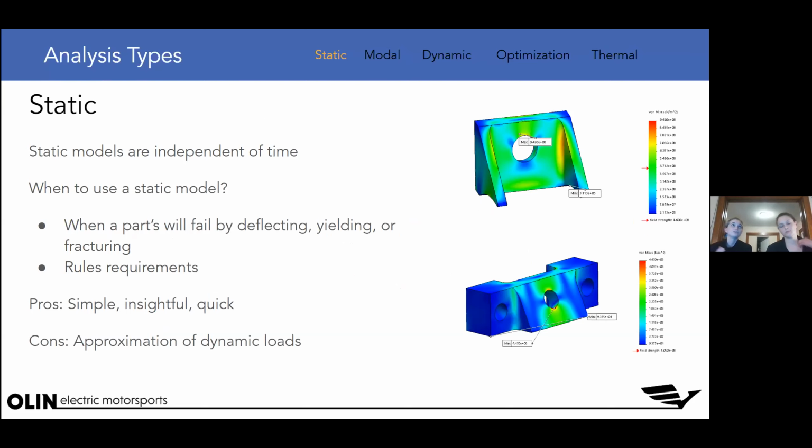you figure out your loads from understanding your system. In this case, in Formula, we tend to know what load we need to meet through our rules requirement. One really important thing that I want to highlight with static modeling is that you can approximate a dynamic load to be independent of time. So that might just mean that the system is constantly changing through time and loads are constantly changing, but for the purposes of simplicity, we can tend to model those as static loads.